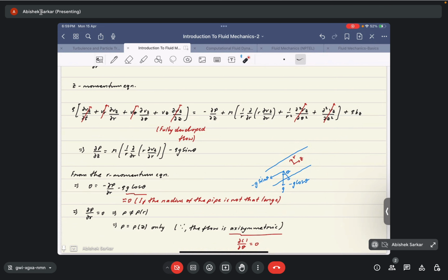So the pressure gradient along the radial direction would be essentially very small if the radius of the pipe is much smaller than the length of the pipe, which is usually the case in pipe flows, right? Because the length of the pipe is much longer than the radius of the pipe. That's why this component of the body force can ideally be neglected in the r momentum equation.